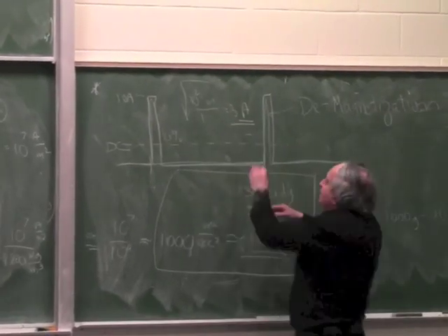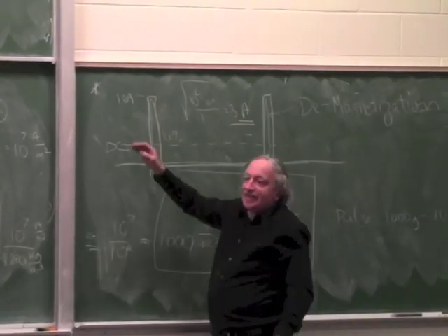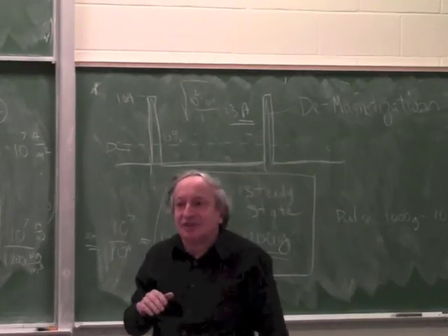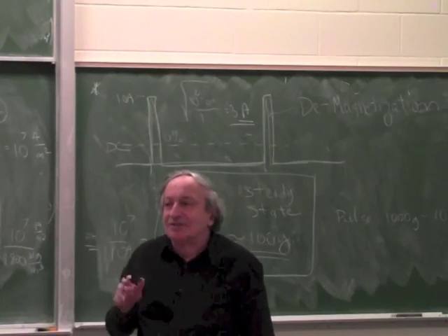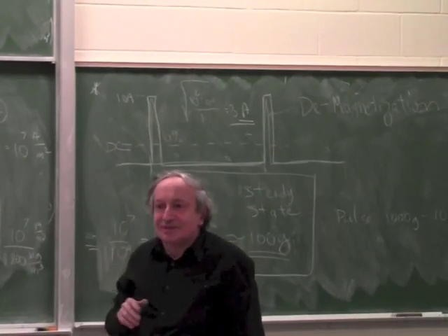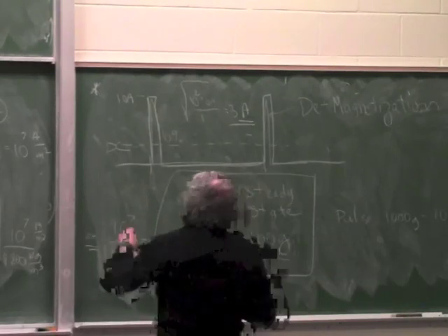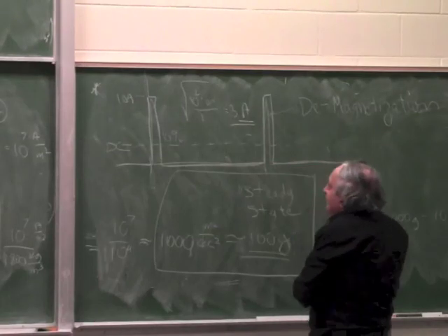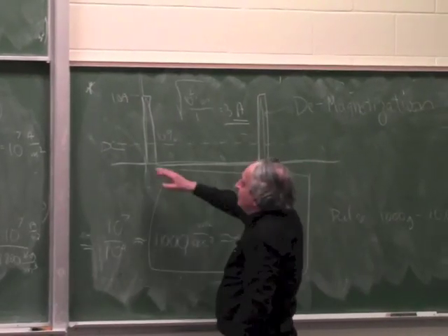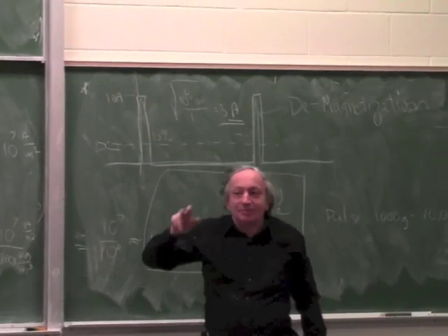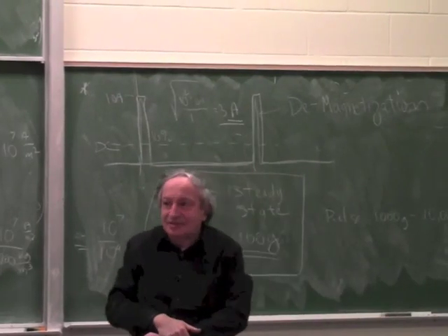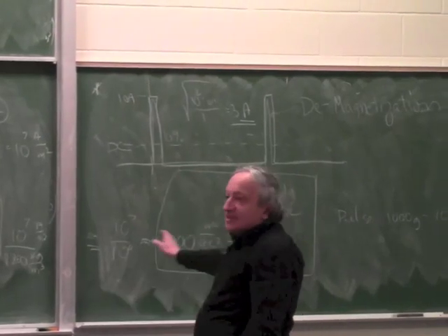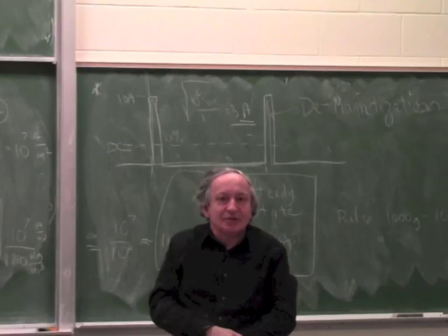So the equivalent heating of that pulse is like 3 amp, and the narrower the pulse, the bigger the ratio between RMS and average, so the more dangerous it is if you pick the average instead of RMS. Say if this was 100 amp for 1% of the time, the average is still going to be 1 amp, but the RMS will be 10 amp. Is that clear? That's very important when you design actuators. Any questions about this? Good. Okay, thank you.